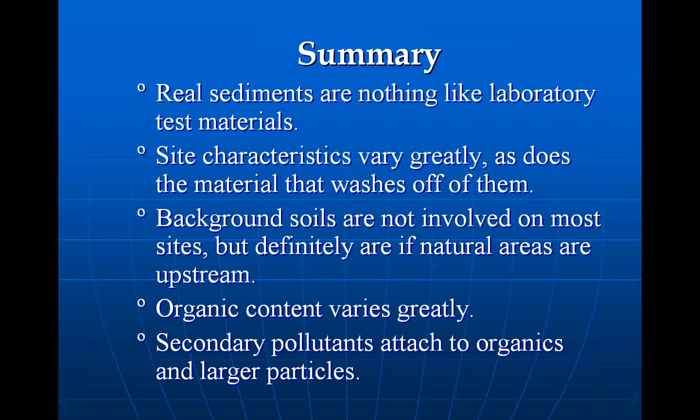There's a time for a lot of media with a tremendous amount of absorptive capacity, a lot of zeolite, a lot of activated charcoal, because of the nature of what's coming off the site. You know, we've found that we're getting very impressive metal and nutrient removal rates by simply using humic material, organic material, coconut fiber, and being able to collect more organics as we go along on that fiber. But everything has a place, but they're certainly definitely not equal.